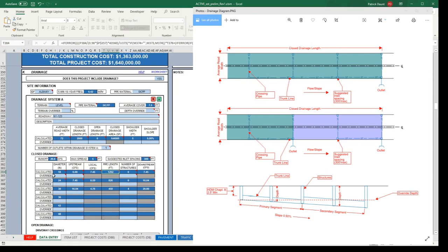So that's, and on top of it, to drive a little further complication into it, we also take into account the crossing pipes, because the crossing pipes have to be accounted for. Crossing pipes are automatically added to the smallest pipe diameter in this table, so this row only. You'll notice that this is significantly larger than the rest of these. That is because every crossing pipe within the network is assumed to be an 18 inch pipe.